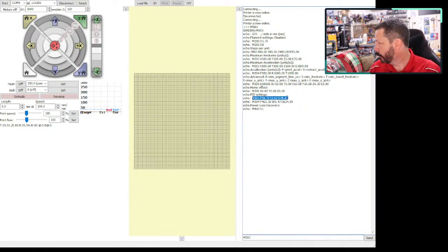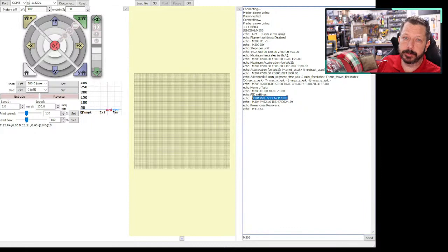So what I want to do is set up my printer in the typical way I'm going to print. So for this printer, it's going to sit on this desk. It's going to print right here. If I ever move it, I might want to do a new tune on it because it'll be in a new location, and maybe there's an air vent that's near it, or maybe it's a hotter room or a colder room or a window or something. So I might want to retune it if I change something. I might want to have different tunings for different filaments. You know, that's possible. I'm going to mostly print PLA and PLA-ish materials on this printer.